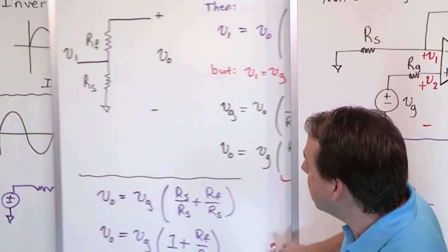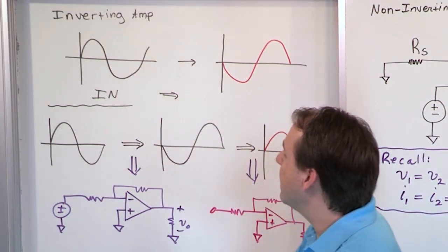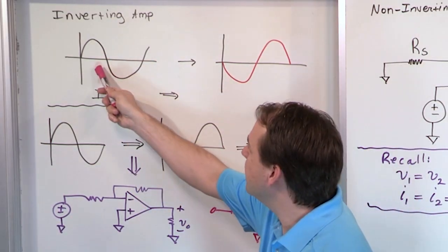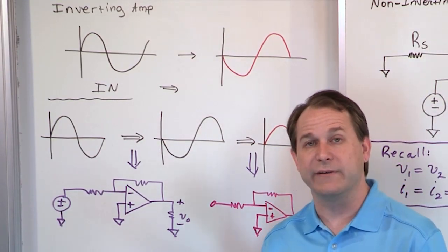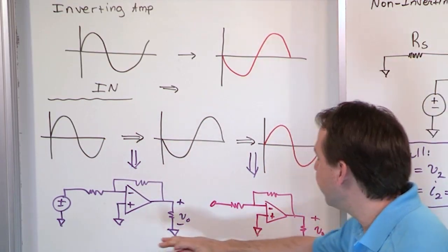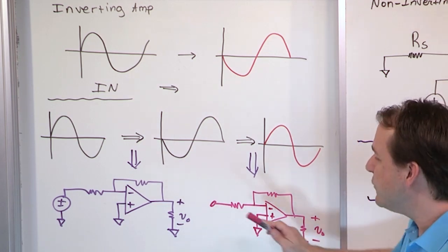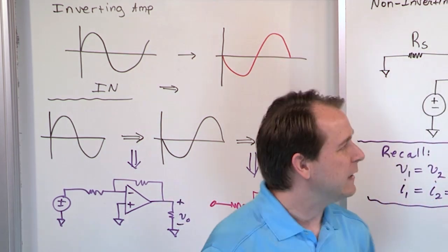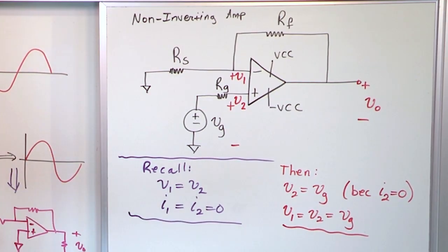Basically what we talked about, just a quick recap, is we had this idea of an inverting amplifier. That's what we were studying all the time. We take the input signal and it inverts to make an output signal. How could you then create an output signal that was non-inverted? Well, you could sandwich these together and put two amplifier stages together. So you invert it here and you invert it again here. But then you have two amplifiers. It makes things complicated. So we say, without proof, that this is what we call a non-inverting amplifier configuration.